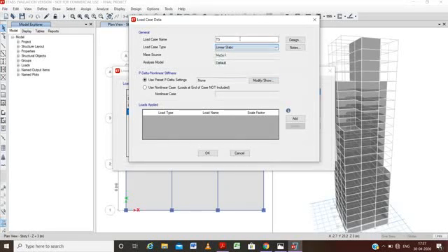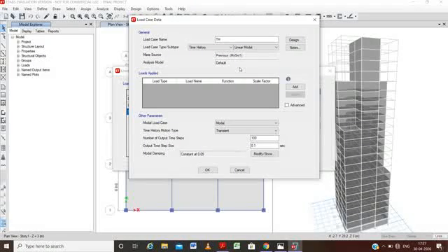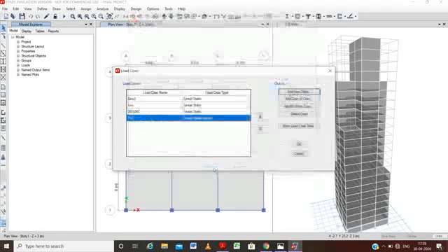Time history method. You will get the time history when it's done, and here it will be added to acceleration U1. The scale factor will be the same, because the scale factor doesn't change whether it is the time history method or the response spectrum method. The output is set, it's all done, and we'll press OK here.